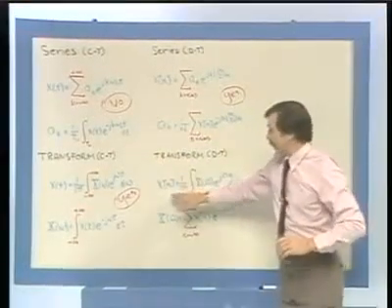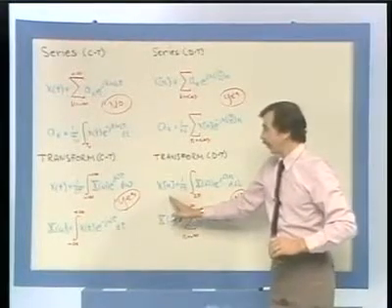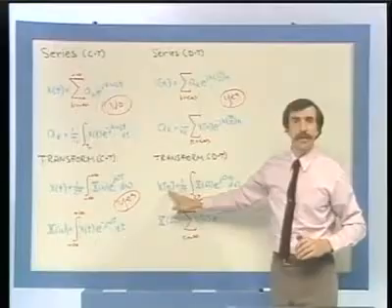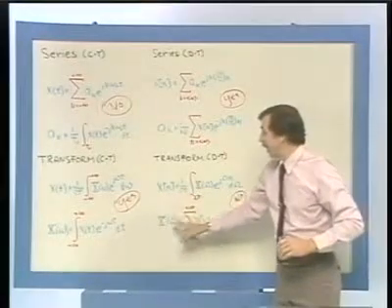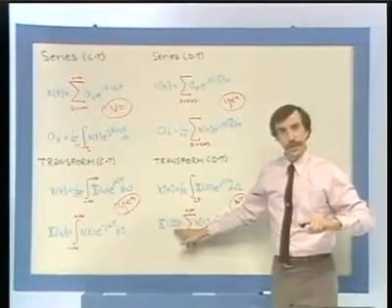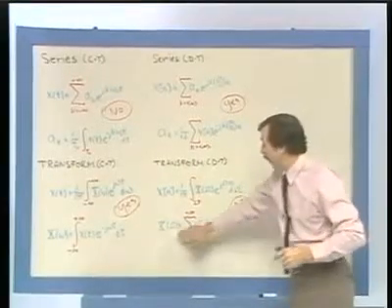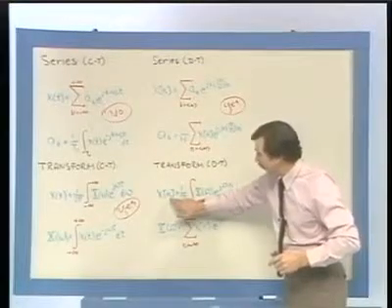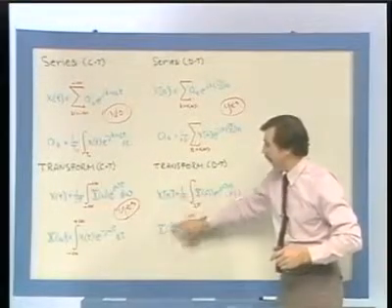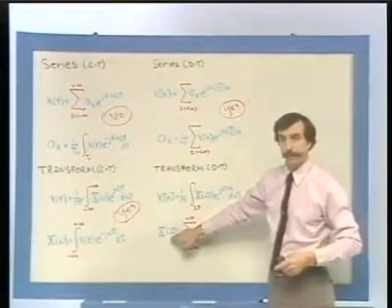In the discrete time case, in the time domain, we have an aperiodic sequence. And in the frequency domain, we have a function of a continuous variable, which we know is periodic. So in the time domain here we have an aperiodic sequence, and in the frequency domain, we have a continuous periodic function.